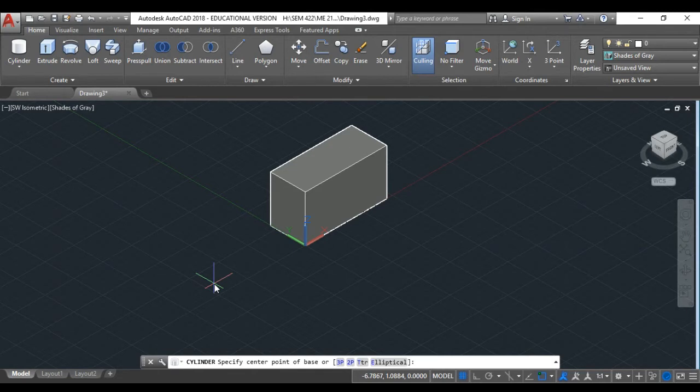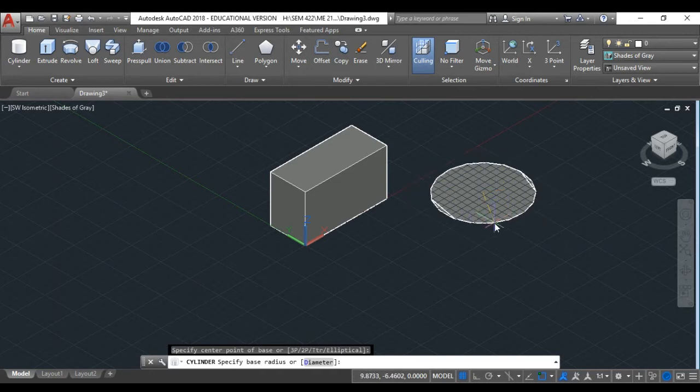What if I decided to draw that cylinder, but not sticking to the ground? It's elevated from the ground. What should I do? In this case, you have to put X, Y, Z, and when it comes to Z, you have to put it as a number. Don't put 0. Clear, guys? Okay, let's try this one. As I told you, if you click anywhere, then by default the program will consider this point as Z equal to 0. But your X and Y is wherever you click.